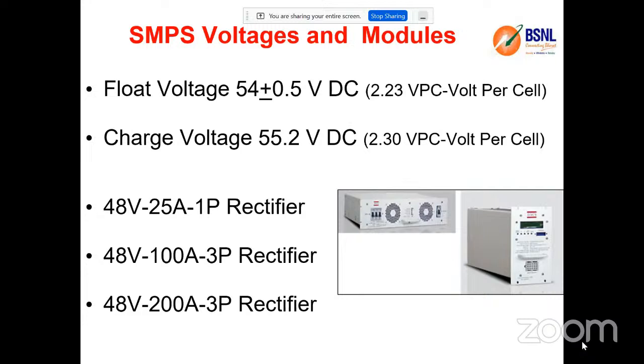But the DC cables look very thick, because they have to carry hundreds and 200s of amperes. Though the voltages are less, to maintain the same power the current rating will be higher, so to carry more current the cables are very thick. In terms of cross section, I would say it is nearly 1.2 centimeters or 1.5 centimeters also.